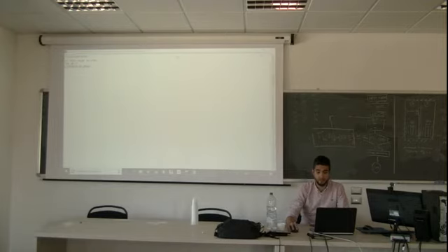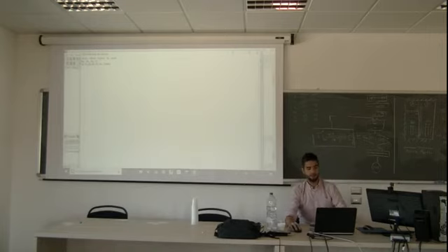You see, we had problems because we just reserved 8 decimals for temperature, and it requires more. The error was fine. Probably the error was lower than that and was moving in that area, so that's why. So we relaxed a little bit, and we got a few more iterations. Remember that with relaxation we had 25,000, now we have 29,000. So the more you relax, the more iterations you will require. But you will be on the safer side.